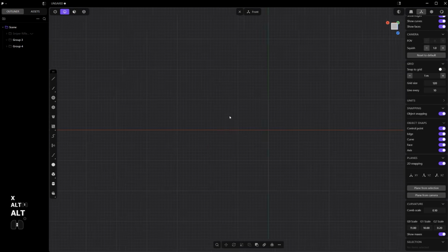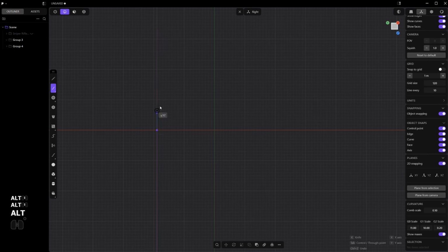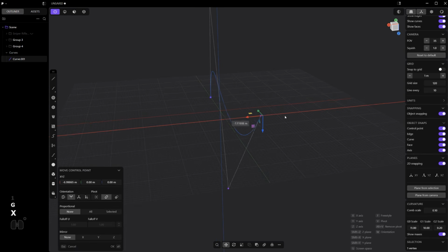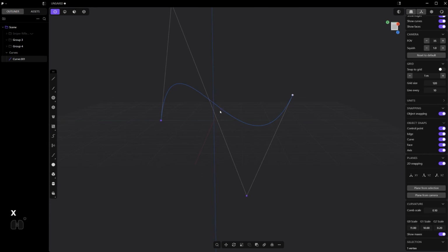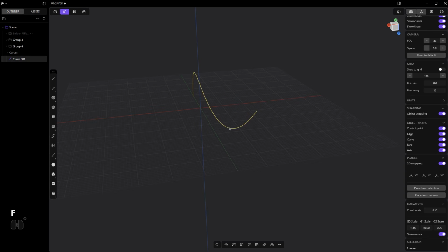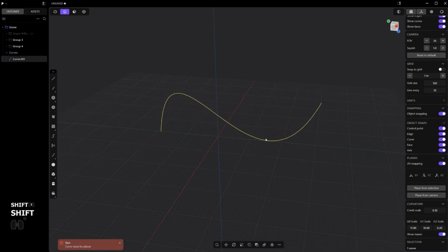But if you have, like I said, a curve that's not planar, it's going to be shifted on all axes, which means it's not planar on either of the axes, right? So it's curved on Y, curved on Z, and curved on X. The slots feature will not work. It will display an error that you need a planar surface, planar curve for this to work.